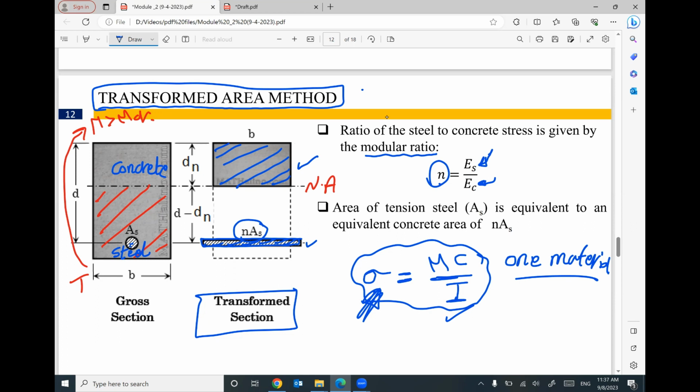Keep in mind, the modulus of elasticity of steel, Young's modulus, equals 30 million psi. Anybody in this room remember the value of E concrete? We covered this last week, I think. 57,000 square root f prime c.